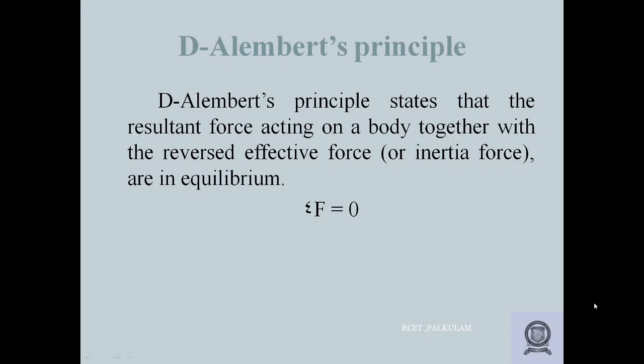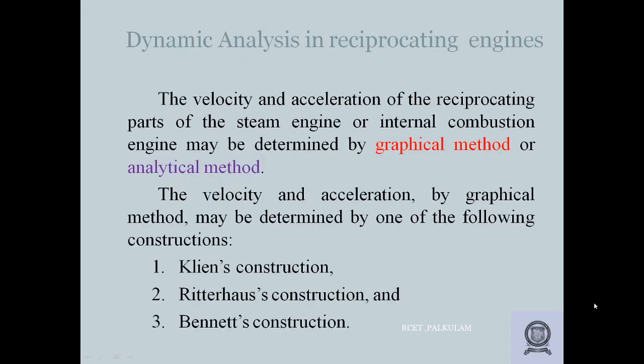Next is D'Alembert's principle. D'Alembert's principle states that the resultant force acting on a body together with the reversed effective force or inertia force are in equilibrium. That is, the total forces should be equal to 0. Sigma F is equal to 0.